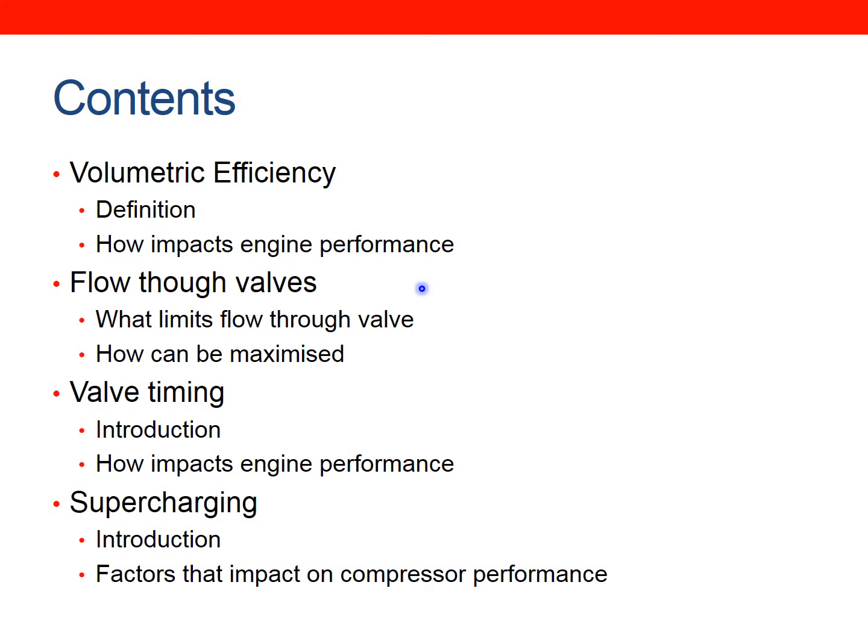Okay, so the contents of this particular lecture. I'm going to talk about volumetric efficiency. I'm going to define it for you and talk about how it impacts on engine performance. And this is really what does drive engine performance, and we'll see that later. I'm also going to talk about flow through valves, what limits flow through a valve, and also how it can be maximized. Valve timing, I'm going to introduce the concept of that and again how it impacts on engine performance. And finally going to talk about supercharging, introduce it, and also talk about the factors that impact on compressor performance.